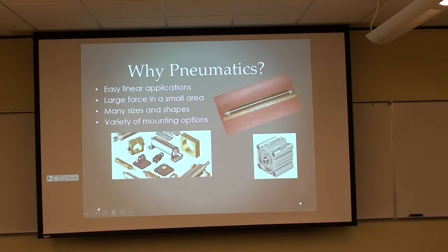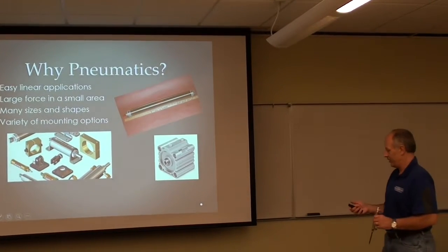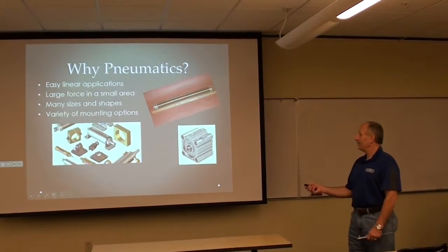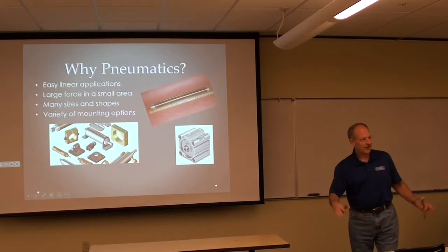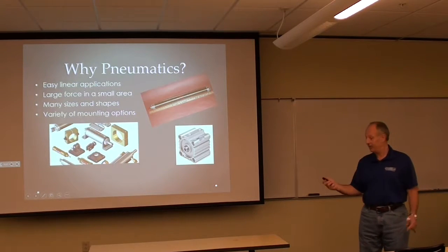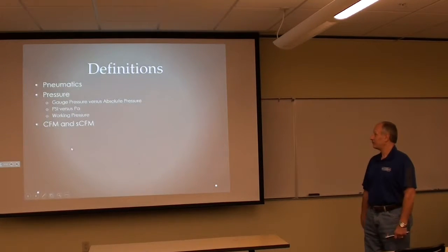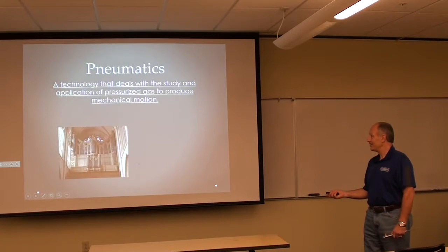Okay, so what's pneumatics? You guys know what that is. And why do we use pneumatics? The right way to apply force in some scenarios. Correct, but linear, right? Most pneumatics are linear, or you can get rotary actuators as well, right? But when you're doing linear, it's so much easier than it is with a motor. The other thing is lots of form factors, right? And lots of ways to do mounting. So it has a lot of flexibility. That's why we use it.